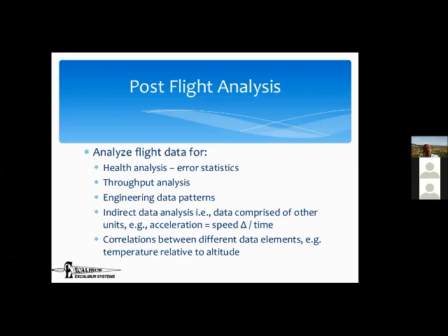So the first thing it'll tell you, actually Merlin will do this too, were there errors? Were there communication errors? So if I see that at the end of the flight, RT7 had 400 communication errors, all of them on bus A, then I know that I have to look at the attachment to bus A. Maybe it's a cable that was attached to bus A, maybe it's the connector, but there's something wrong there, and I know I have to look for it.